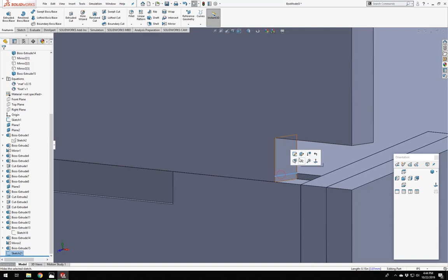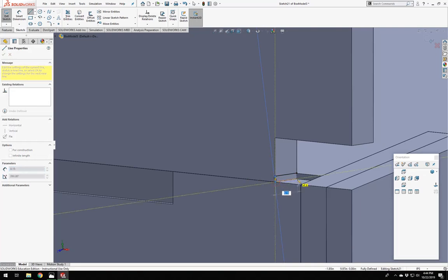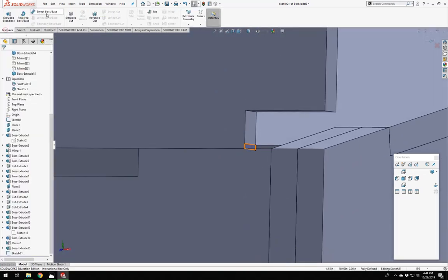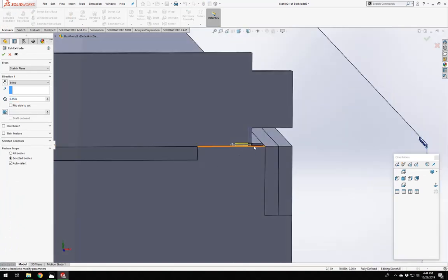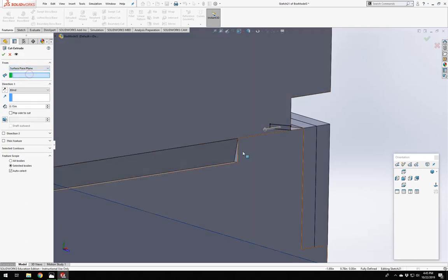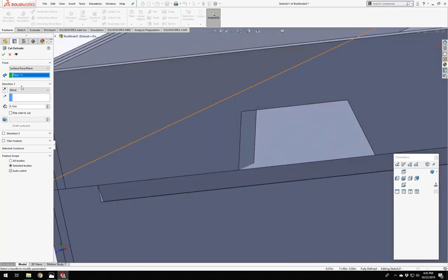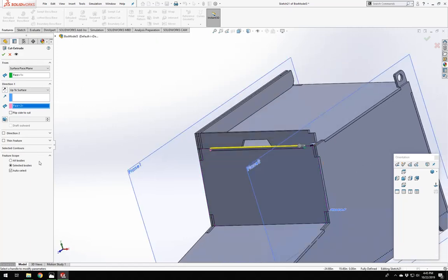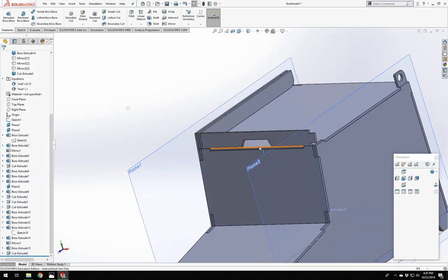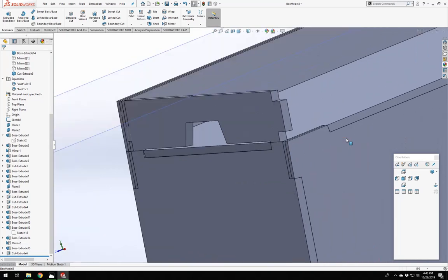And we're going to do this slightly differently. So going back in, editing our sketch, we are going to finish this off as a square. There. Yes. Yep. And so now we're going to do the extrude cut again. But instead of being from that plane, we actually want it to start here. And so we can do that by selecting from surface plane. And so we want to say actually from this surface. And we just want to go all the way up to that one. So we can say up to surface and that surface. And make sure that we select just the body we want to cut. Whoop. So now we actually have this where we'll make sure that we clear this top face, but we'll actually kind of nest into those, which I kind of like.